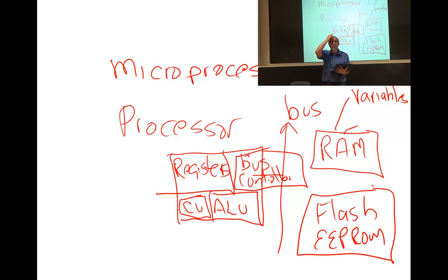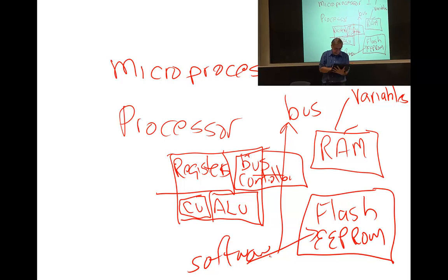What else do we put in RAM? One more important thing. The program you're computing. Where's the software go? The software is going to go in here, because it's an embedded system. On this laptop, the software is in RAM. But this semester, we're going to put our software into ROM. So when we turn the power on, it will become whatever it's supposed to be. One more important thing. The stack has to go in here. You could have the heap. But those are the things in RAM.